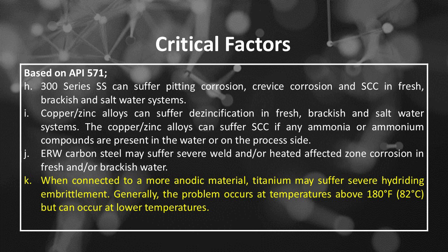Number K, when connected to a more anodic material, titanium may suffer severe hydriding embrittlement. Generally, the problem occurs at temperatures above 180 degrees Fahrenheit, or 82 degrees Celsius, but can occur at lower temperatures.